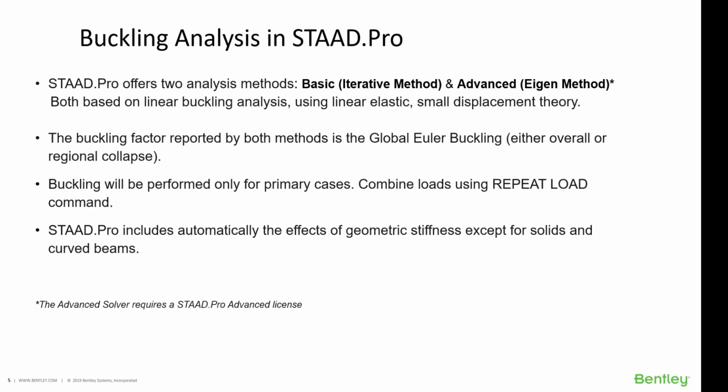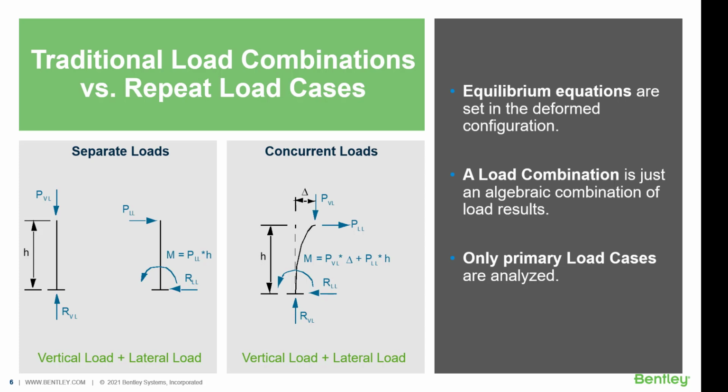STAAD.Pro includes automatically the effects of geometric stiffness except for solids and curved beams. The advanced solver requires a STAAD.Pro advanced license. It is important to remember the difference between load combinations and primary loads.